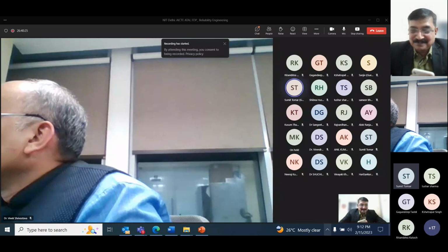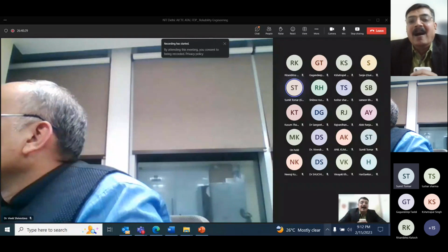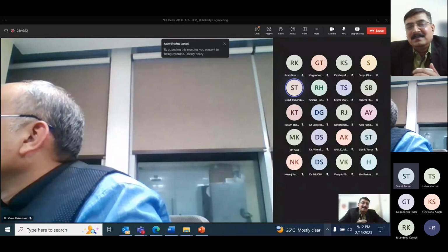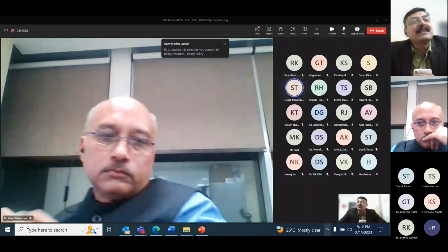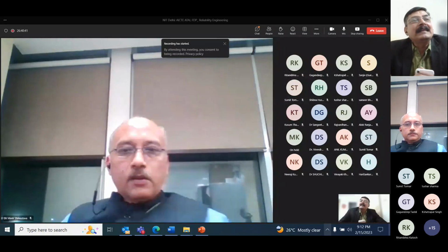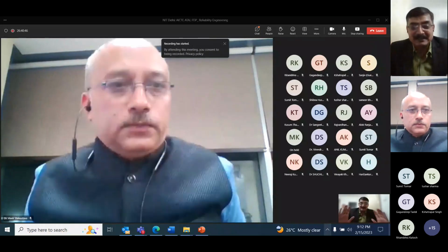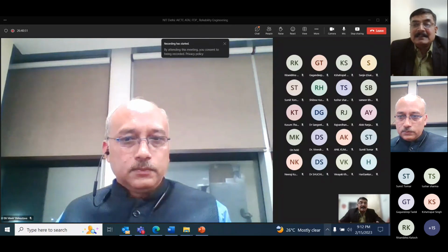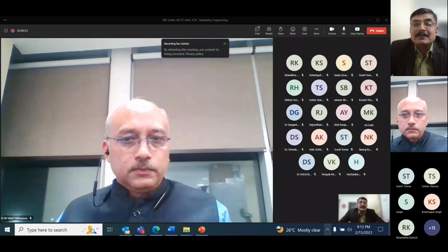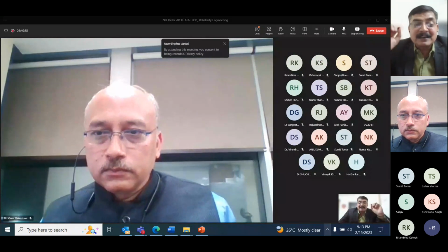Tell me, please. Sir, if I have a mission critical system and somebody asks me what kind of reliability is expected from it, what are those parameters based on which I can calculate the value for my system? So for mission critical systems, the reliability of the safety function is different. Try to understand, there is a different kind of metrics. In mission critical, safety critical systems, there is a concept called the safety integrity level, SIL. We call it a SIL rated product.